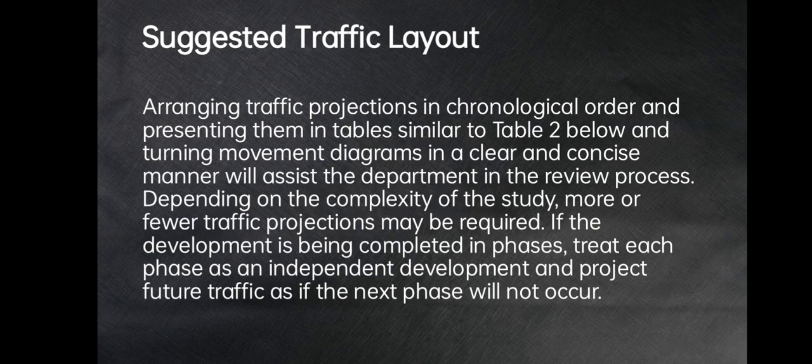Suggested traffic layouts. Arranging traffic projections in chronological order and presenting them in a table similar to Table 2 below, and turning movement diagram in a clear and concise manner will assist the department in the review process depending on the complexity of the study. More or fewer traffic projections may be required if the development is being completed in phases. Treat each phase as an independent development and project future traffic as if the next phase will not occur.